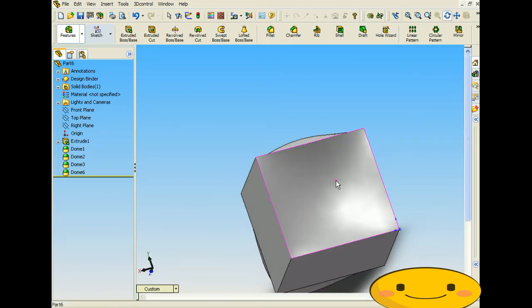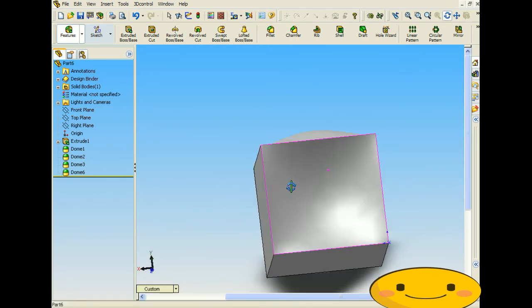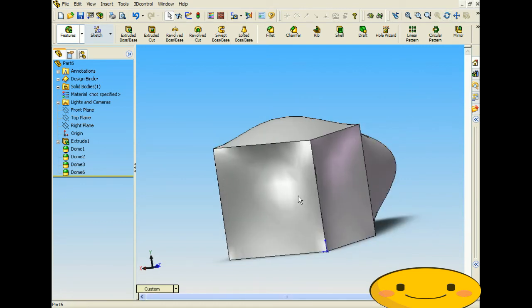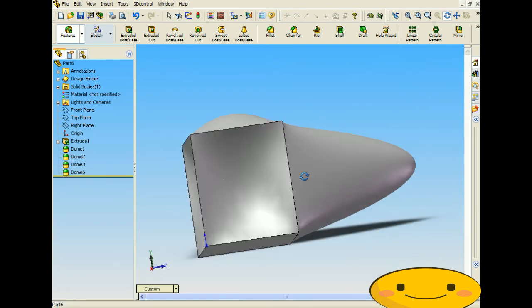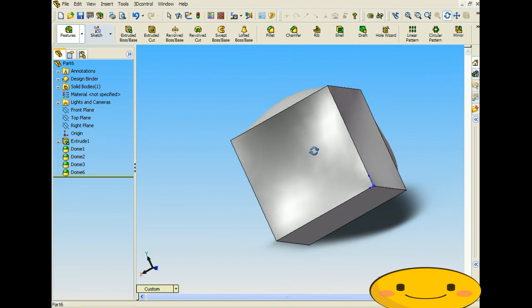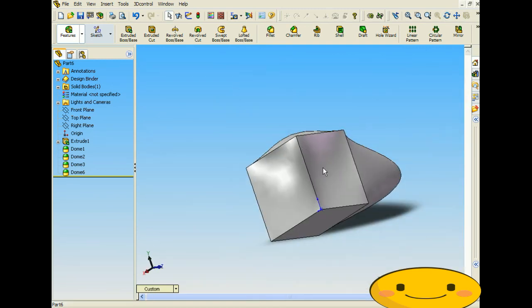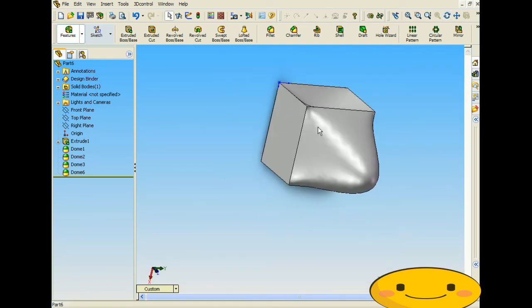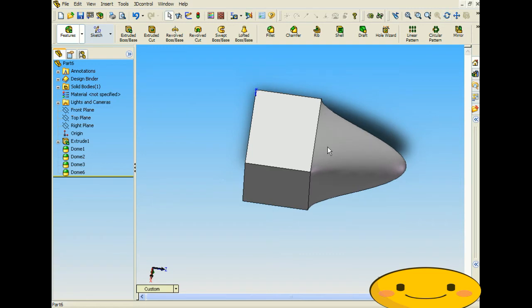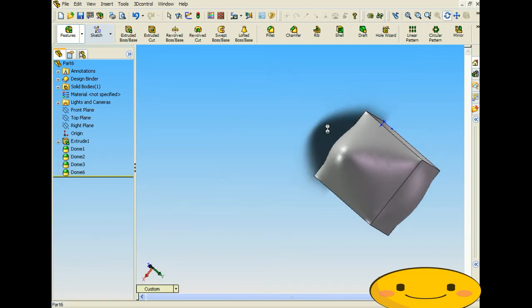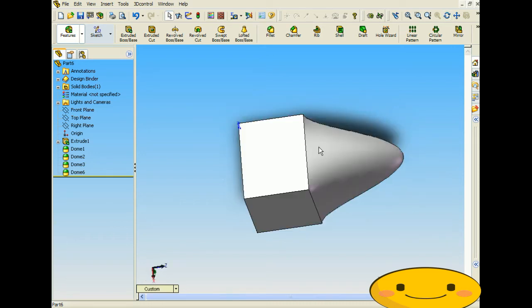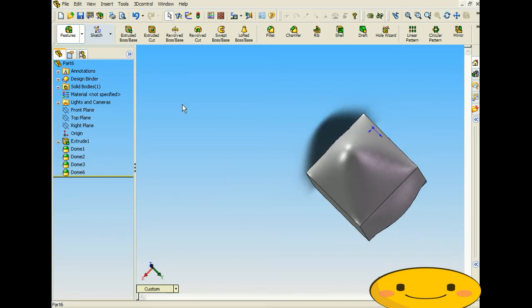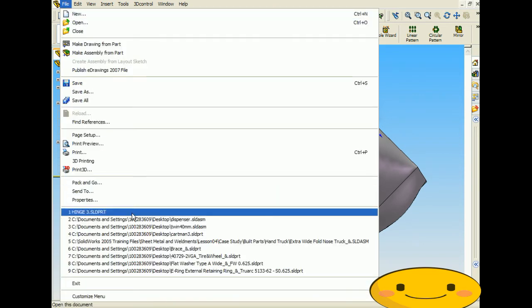You're going to have to play around with the sizes and how much you're going to cut in so it doesn't destroy everything else going on there. So we've got a 10 mil dome again there. But you're able to play around with it and you're able to cut in something such as this going in. So you're able to do it to surfaces such as these ones, but you're also able to do it to more intricate surfaces. So the hinge that we opened up in the last tutorial, let's open it up too. Let's click File and open up the hinge. It's on the DVD.